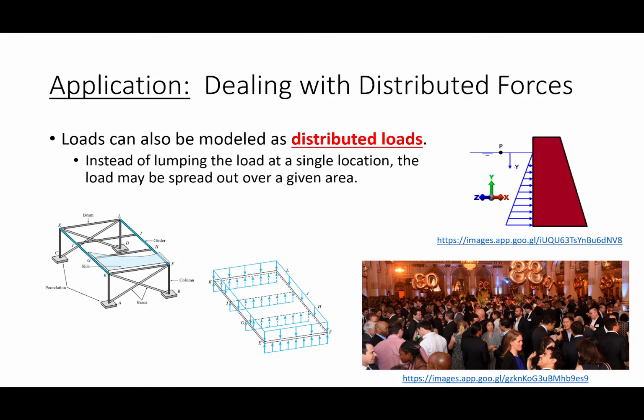You can calculate the pressure at a given depth by basically just taking the depth and multiplying it by the unit weight of the fluid, right? So for example, if you were 10 foot deep in water, the pressure would be 10 foot times 62.4 pounds per cubic foot, because 62.4 pounds per cubic foot is how heavy water is, okay? So what the structure would see is a distributed load, but it would be triangular in nature, okay?